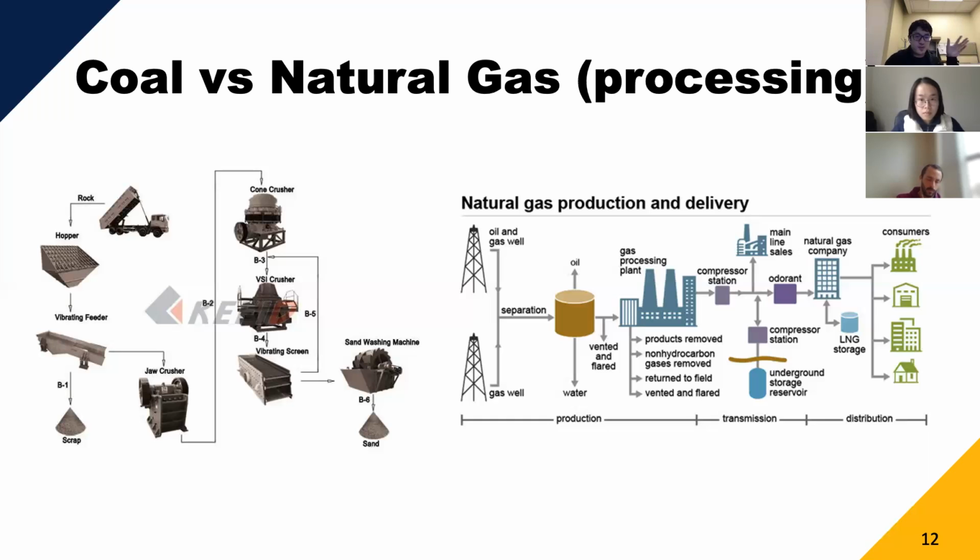The most efficient way of doing combustion is to grind up your coal into a fine powder. It increases surface area and allows for more consistent and faster combustion of your carbon material.